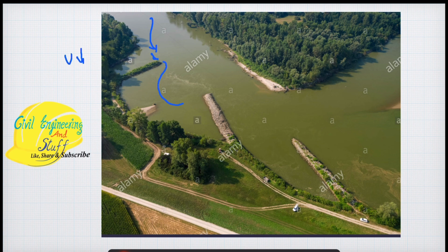Again, the water is moving, and again it strikes another groyne. The velocity will be reduced again, and like this the process keeps on going. With this regular decrease of velocity, the velocity with which the water strikes the bank is very less. So the probability of silting reduces to a much greater extent.